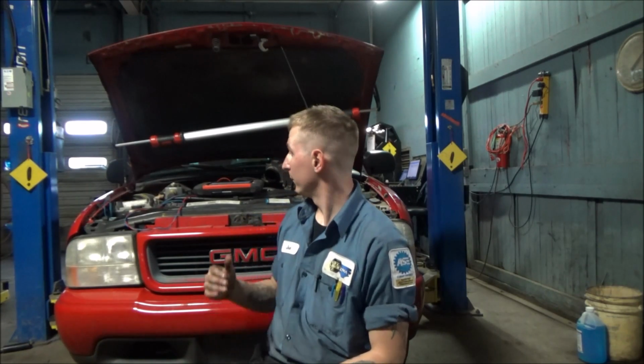As far as what the engine computer is actually looking at regarding inputs to determine if the system is working or not, we confirmed that is oxygen sensors. So we did some really down and dirty quick tests to troubleshoot this issue. We used some basic logic to determine what was working, what wasn't. And ultimately, we ended up going directly to the air pump motor itself and doing some tests there. And we confirmed that we have a bad air pump solenoid as well as a bad air pump motor, likely caused by the transmission fluid leak that we saw in this vehicle.